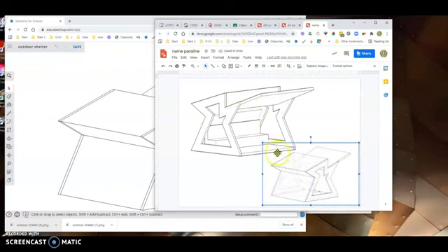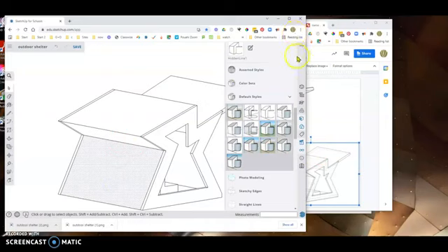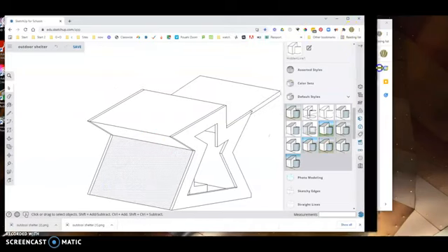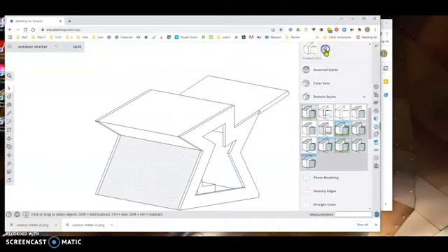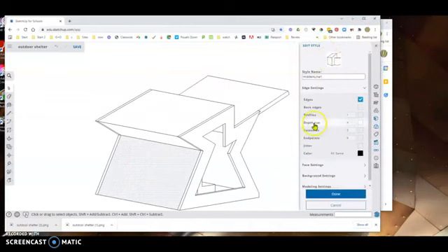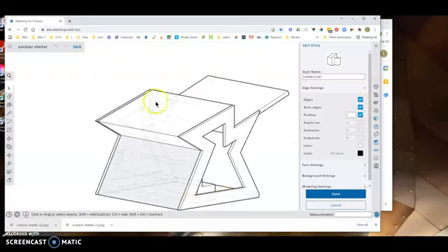It would be good if I showed the hidden detail on here. One thing I didn't do on this drawing is I didn't lift up the profile edge. So just lifting that to 2 and putting in those back edges, it just gives it a much better quality of line drawing rather than just having all the same line work.